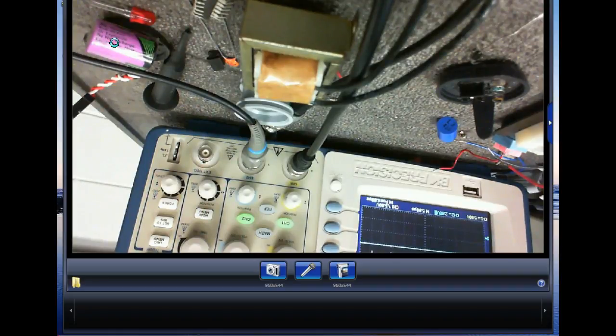You would be spending hours just trying to get the goop off the thing so you can make measurements on it. If you think how much money you make an hour at your job, of course, if you've got the time, that's fine. They're hard to troubleshoot because of the feedback circuit. Design is not a big deal because you can buy the switching mode regulator chips. Then all you do is add a few external components, so they're not hard to combine.